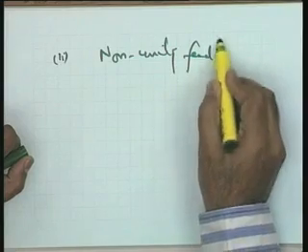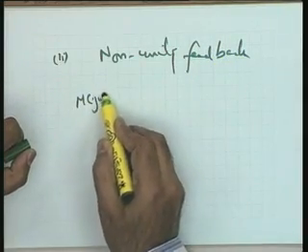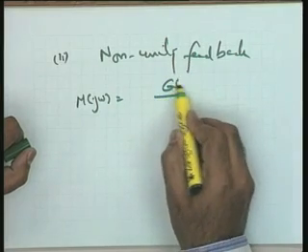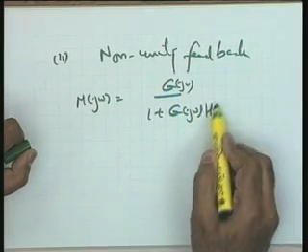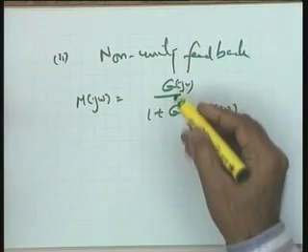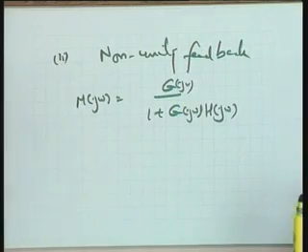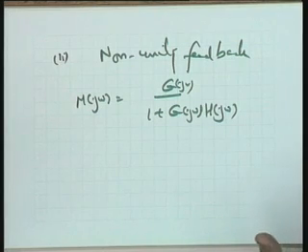In the case of non-unity feedback, what are we going to do? You see that in this particular case, M(j omega) is equal to G(j omega) over 1 plus G(j omega)H(j omega). Please see that the M circles, and from there the Nyquist chart, you have got are for G over 1 plus G and not for G over 1 plus GH. Unfortunately, the symmetry does not work out for the closed loop system, for the non-unity feedback system.